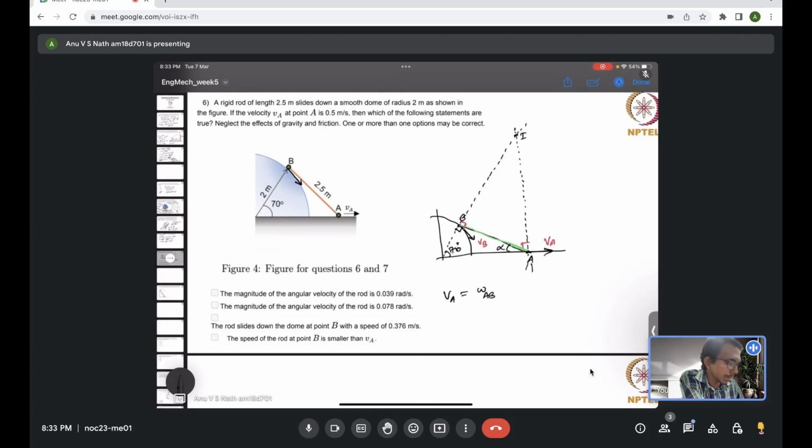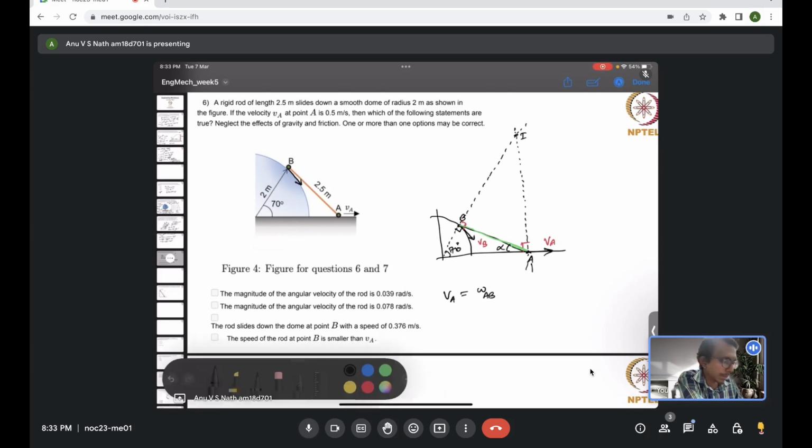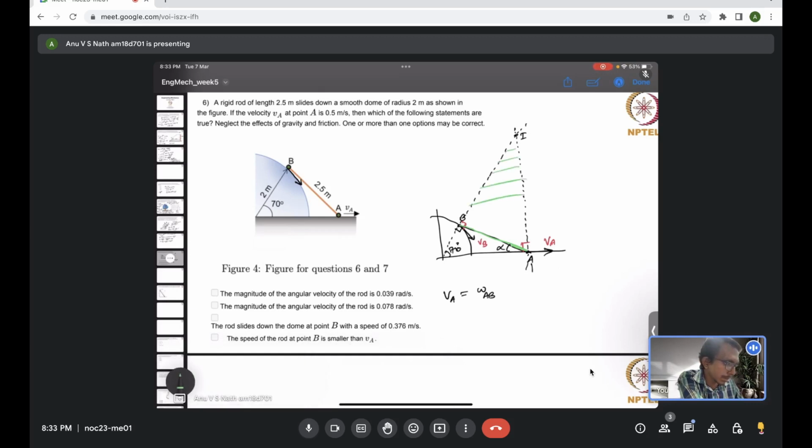So basically, if you see, you can assume that member AB along with the I is making a triangular piece, right? It's an imaginary piece there. So you can think of this as a single piece, just that that part is missing. This entire triangular piece is a rigid piece which is rotating, pure rotation, about the instantaneous center, right? That's the definition actually. This piece is actually absent, it's happening only at that instant. Next instant there will be another piece which is forming with a different instantaneous center.